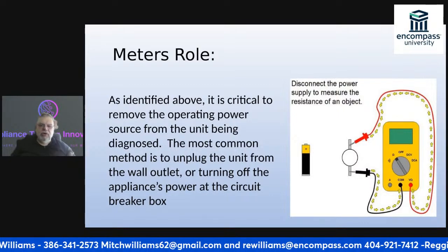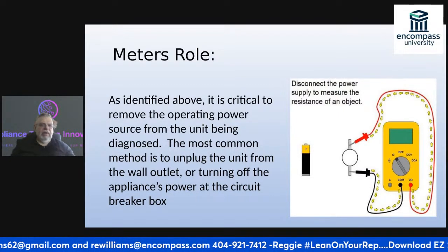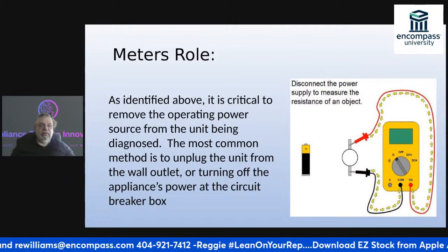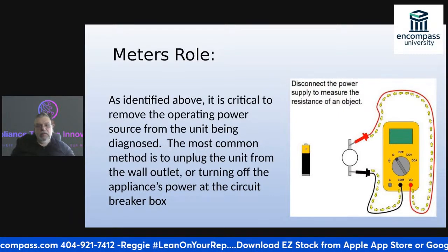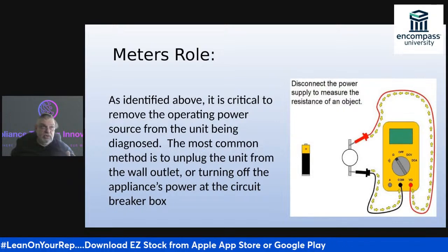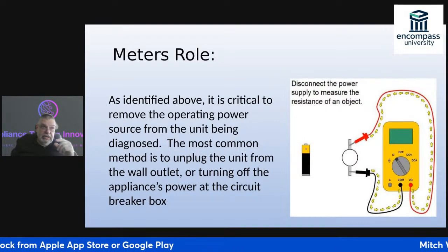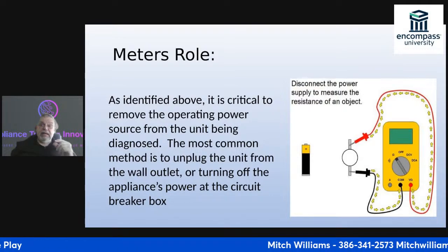If I'm trying to measure resistance, I will blow my meter up if I have it plugged in. Mine, the one that I like to use, has a little fuse in case I get stupid one time and forget to do it. And I have blown that little fuse a couple of times because I got in a hurry.